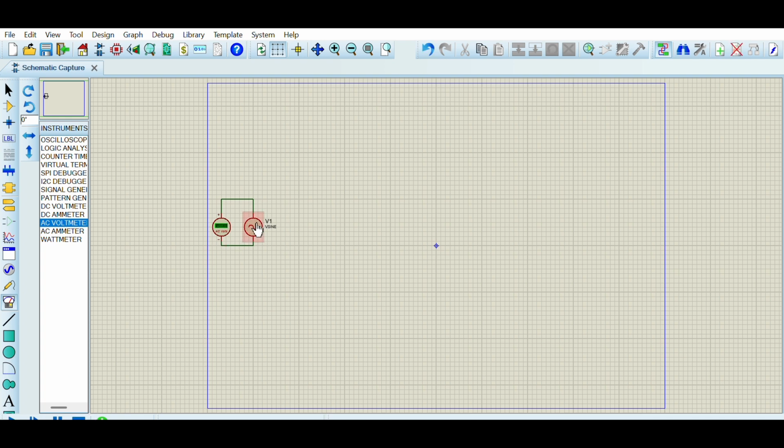So we can just stop the program, go to properties again, keep the frequency at 50 but the amplitude at 310 or 320. Let me do 320 first. Let's run the program and see how much 320 goes for. A bit too high, so I'm gonna stop it. I'm gonna change it back to 310, see how 310 with 50 Hertz behaves. Goes 219. Well, I'll take it.